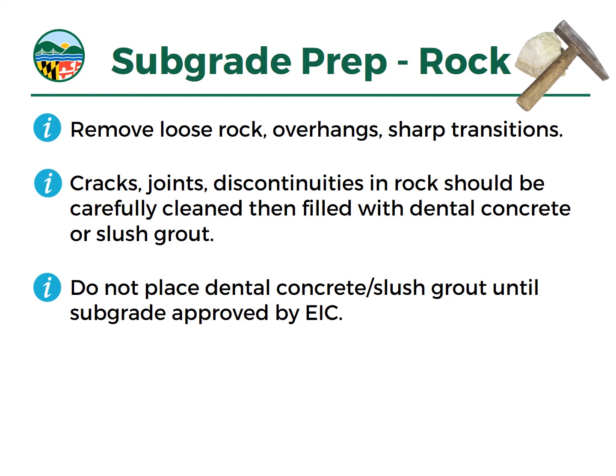and then we want to cut off and seal any of those cracks or joints or discontinuities in the rock. Recommend filling them with dental concrete or slush grout so that we've got a nice impervious surface to work on. But before you place that slush or grout, make sure it's approved by the engineer in charge.